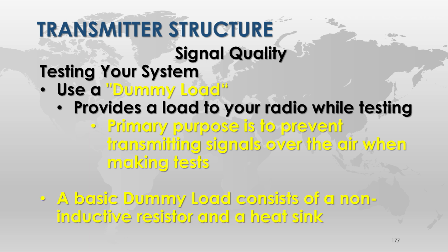Yeah. A basic dummy load consists of a non-inductive resistor. Now, a wire wound resistor is going to be inductive. It's going to be frequency sensitive. It can't help it. And a heat sink. So it's got to be non-inductive and a heat sink. So you could make your own out of a paint can and some mineral oil. A paint can full of mineral oil with a hole in the top, sealed, and all the resistors down inside. And the oil acts as the heat sink for the heat produced by the resistors that are absorbing all the power going out. They actually sell kits that you can buy that come with the mineral oil, or you can buy one where you go out to Walmart and buy your own mineral oil.